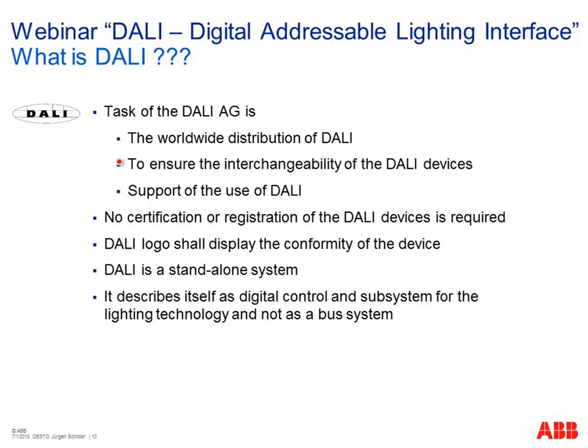And in general, of course, support of the use of DALI is the target of the DALI working group. If a manufacturer develops a new component, it's not necessary to certify or register such a DALI device. There is a test procedure behind it to more or less check if it is in compliance with the DALI rules, but not like KNX, where you have to register and certify a KNX product at an independent registration or a laboratory, let's say.